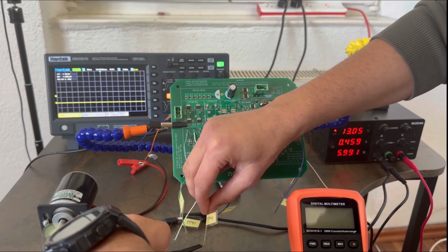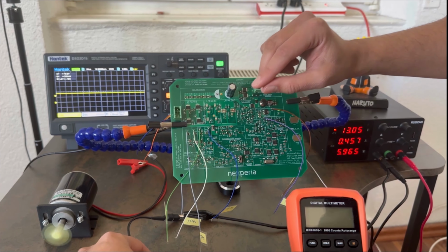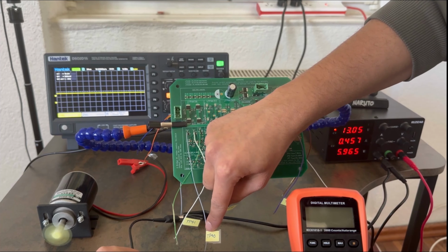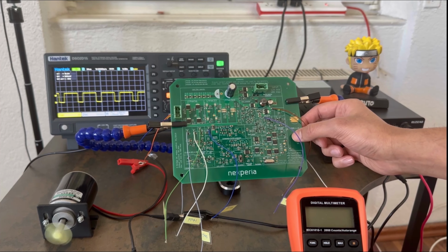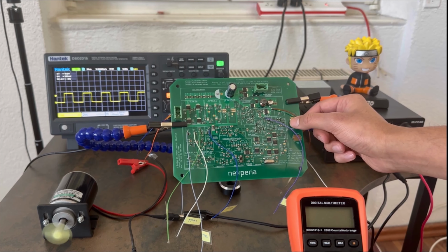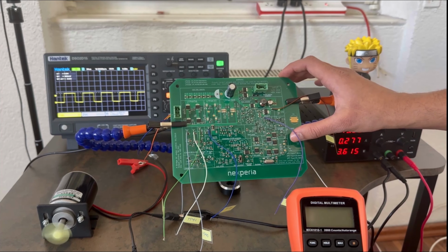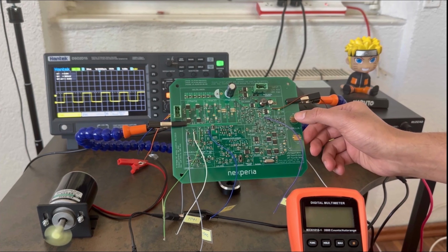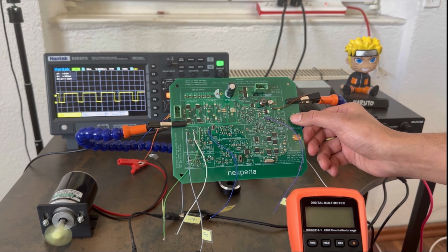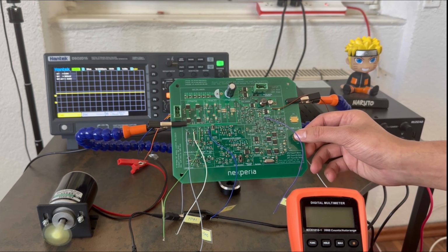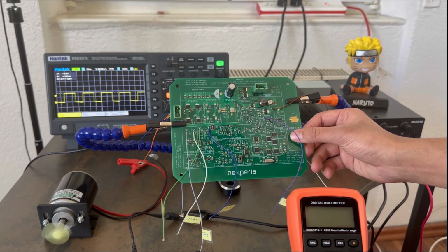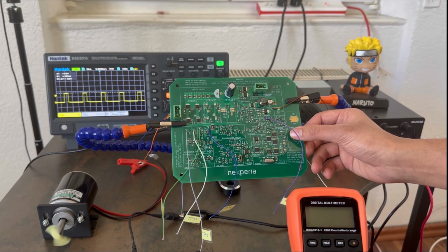Well, if the motor is running, that means Q3 should be turned on with PWM. Let's see that as well. Cool, we can see the PWM across Q3. As I change the speed of the motor, the pulse width is also changing. If I increase the speed, the duty cycle increases and at last Q3 turns on fully with maximum motor speed. If I decrease the speed, the duty cycle decreases to a minimum and eventually the MOSFET Q3 turns off and motor stops rotating.